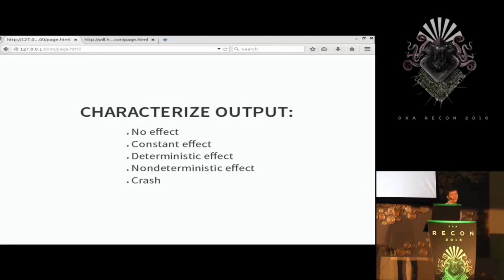There are deterministic effects, for example, an ALU operation where you add 2 input registers that you control and you can predict what the output value will be. There are non-deterministic effects, which only appear non-deterministic because hardware usually is deterministic. So unless you think for a good reason that there's RDRAND or RDTSC equivalents down in your particular target, it probably means there's input state that you're not controlling yet.